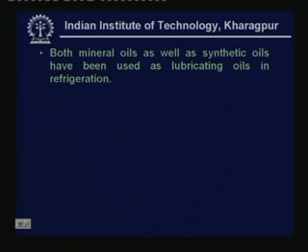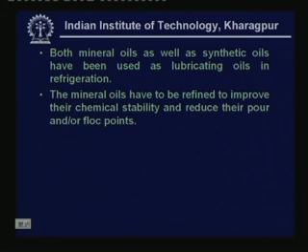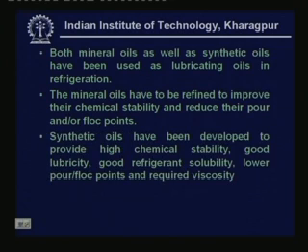And both mineral oils as well as synthetic oils have been used as lubricating oils in refrigeration. Mineral oils have to be refined to improve their chemical stability and reduce their pour or floc points, okay. You cannot use the mineral oils in unrefined form, you have to refine them. And synthetic oils have been developed to suit the requirements of chemical stability, good lubricity, good refrigerant solubility, lower pour or floc points, and required viscosity. That means you can synthesize oils to suit your requirements.